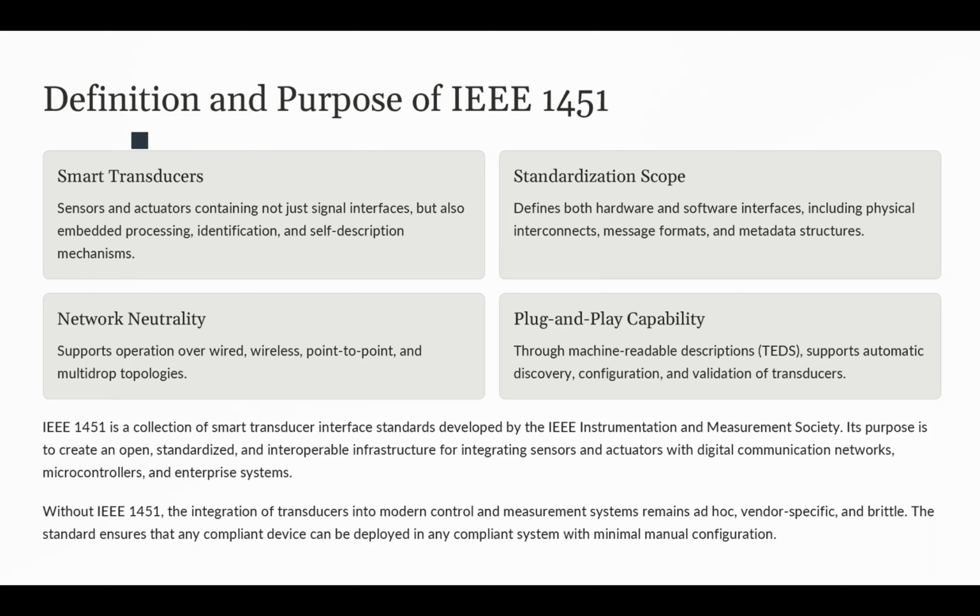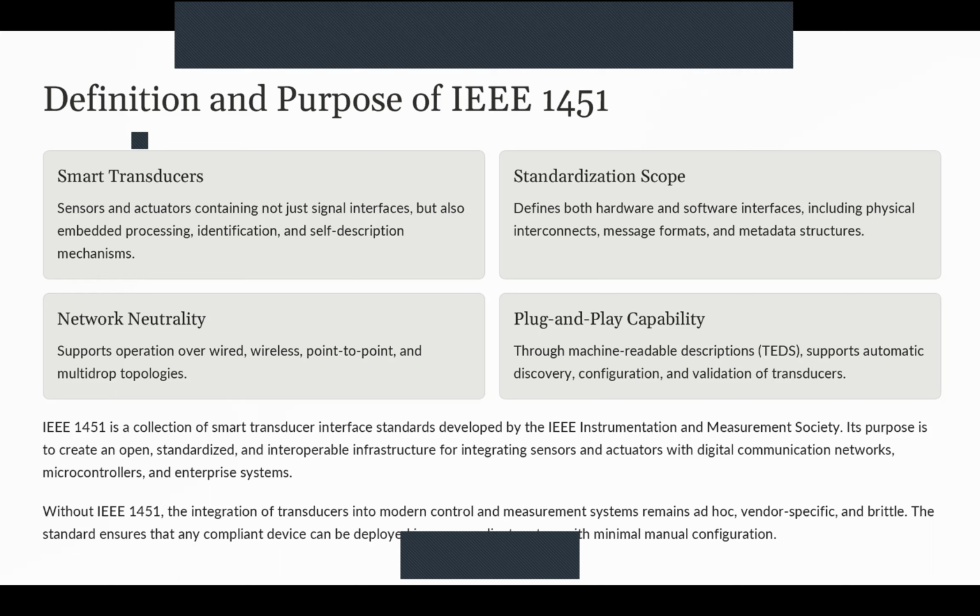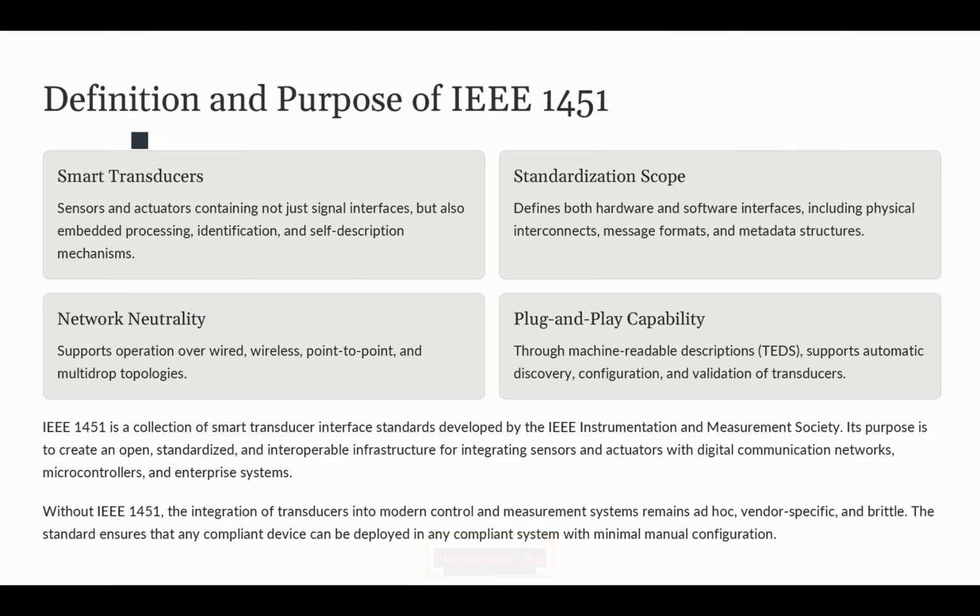Now, these standards define both hardware and software interfaces. So it includes the physical connection, the command structure, and the transducer electronic data sheets, which we call TEDS. And basically it made them work over wired or wireless or point-to-point systems. So it basically provides a plug and play capability using machine-readable metadata.